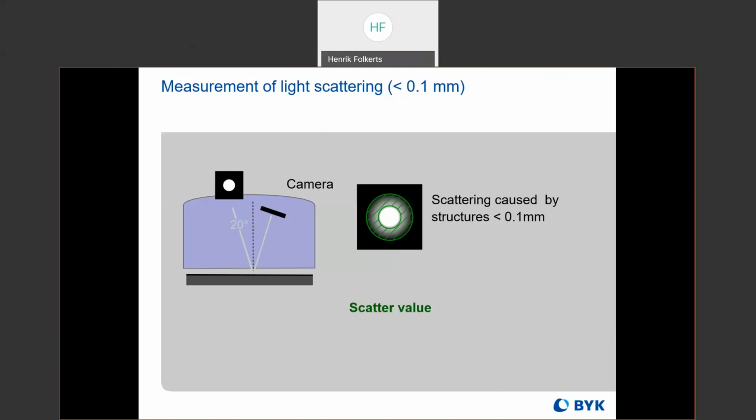Next question here from Mike. For measurement accuracy of the laser and camera, is it recommended to only roll the wave scan forward when taking a measurement, or is it okay to roll backwards also? It's generally preferred to roll forward, but you can roll backwards. Sometimes you do have tight spots that need to be measured, and you kind of have to roll back and forth to get the desired length. So it's acceptable, but not preferred.